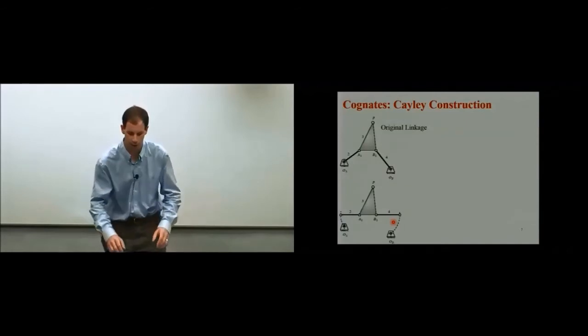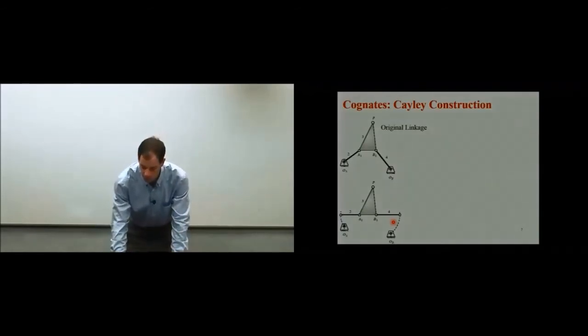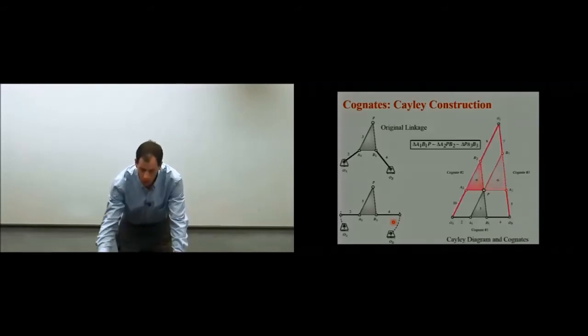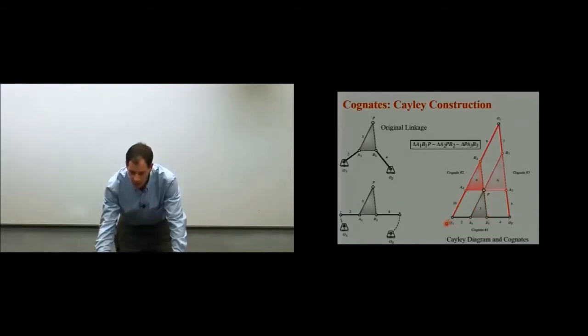So all 3 of those pivots, the 2 grounds and the 2 moving pivots, are all collinear. So I've unpinned this. And then I take this unpinned mechanism, so that's links 2, 3, and 4. And first of all, I take my coupler and I create a similar triangle that goes from ground pivot on the A side, ground pivot to the B side. So that's the base of that, the moving pivot to moving pivot of my coupler.